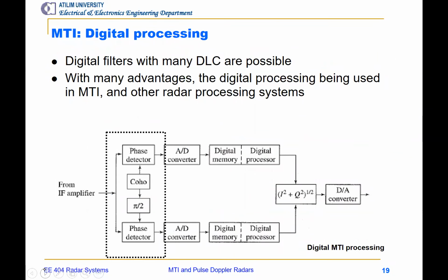Okay, let's go into the details of MTI digital processing and show how to design a phase detector. Remember that the phase detector was the main component in MTI processing. We have to trace the phase variation in order to extract the frequency change, so the Doppler frequency.